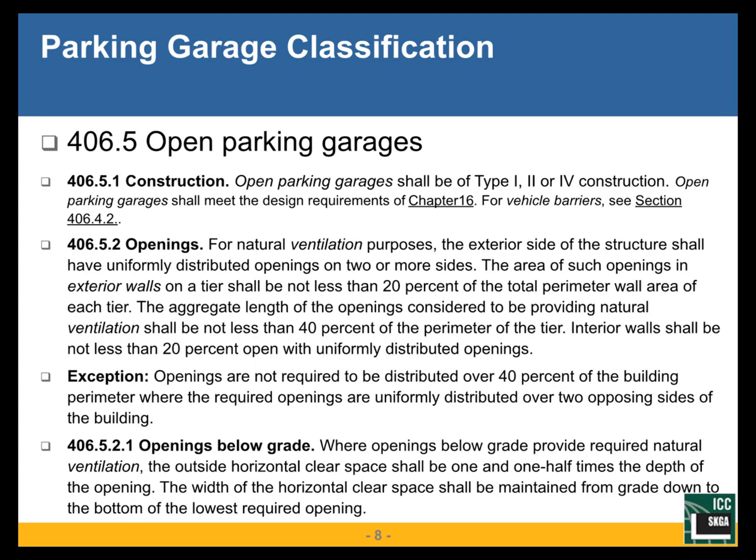Open parking garages in 406.5.1 require that the garages be either type 1, type 2, or type 4 construction and meet the design requirements of Chapter 16, which are structural requirements. There are additional notes for vehicle barrier requirements in Section 406.4.2.